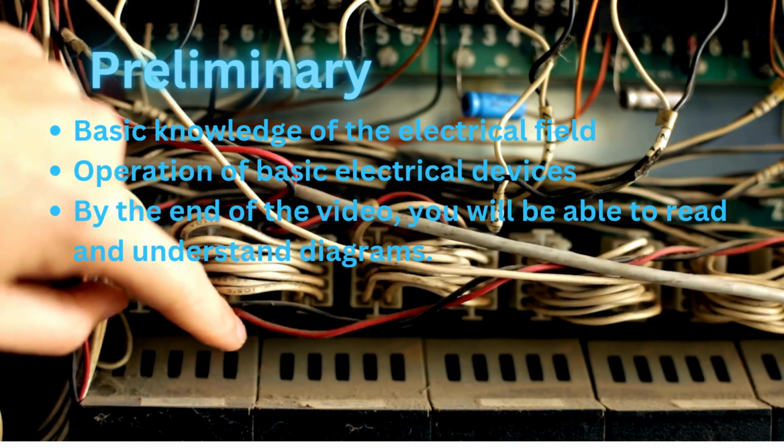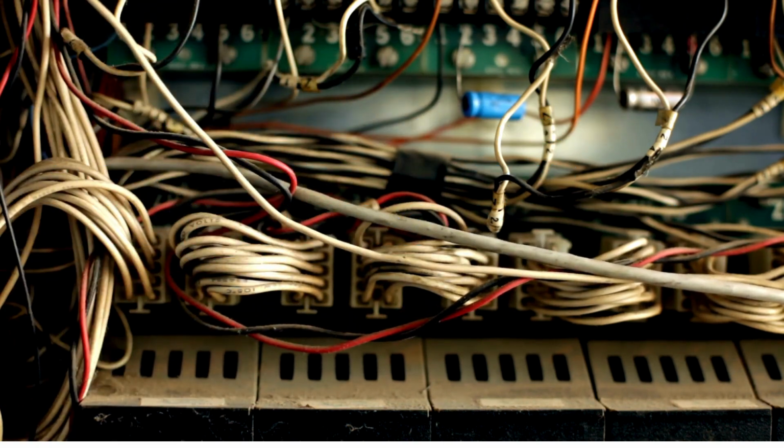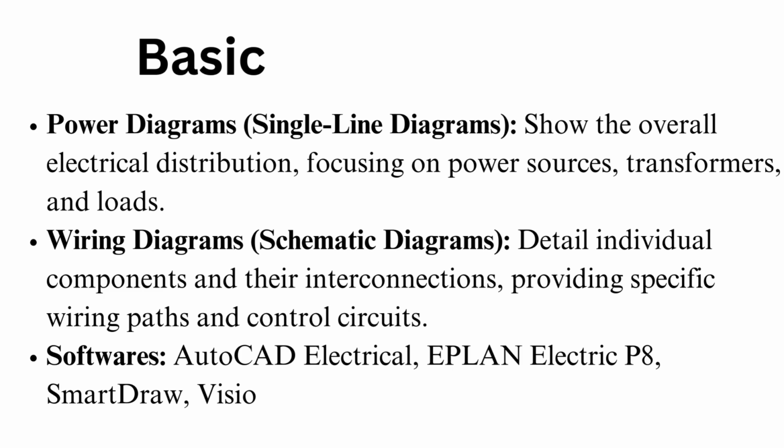of an electrical system. This is the first video where we will explore the power and control diagram of a 415 volt induction motor, which is relatively simple to understand and consists of two pages. In the next video session, we will cover the 6.6 kV induction motor diagram, which is more complex, with 6 pages. The wiring diagram could be 1 page to 100 pages depending on the system requirement.